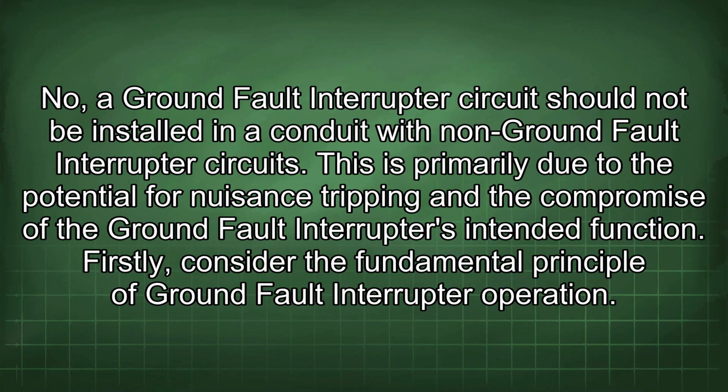No, a ground fault interrupter circuit should not be installed in a conduit with non-ground fault interrupter circuits. This is primarily due to the potential for nuisance tripping and the compromise of the ground fault interrupter's intended function. Firstly, consider the fundamental principle of ground fault interrupter operation.